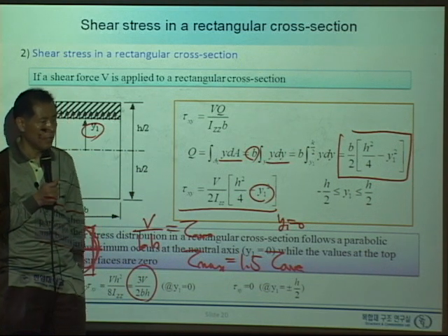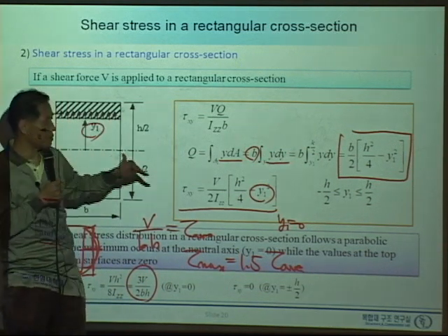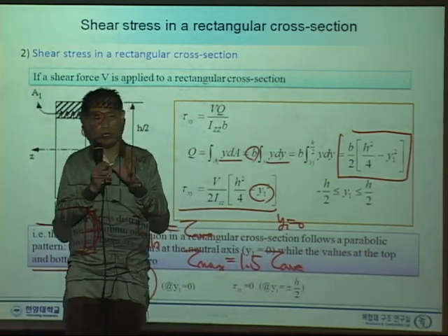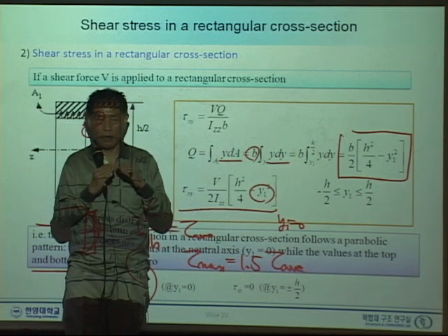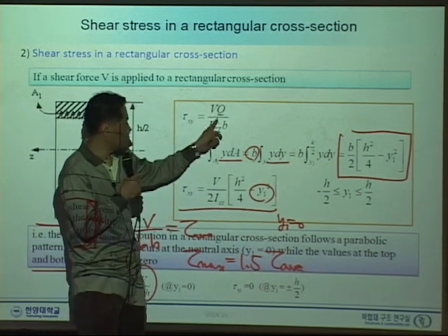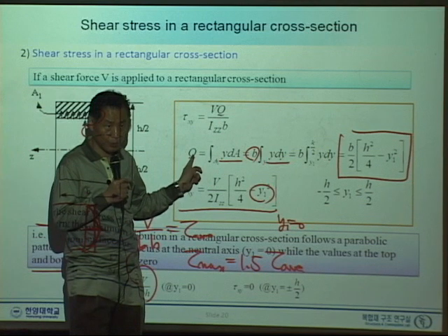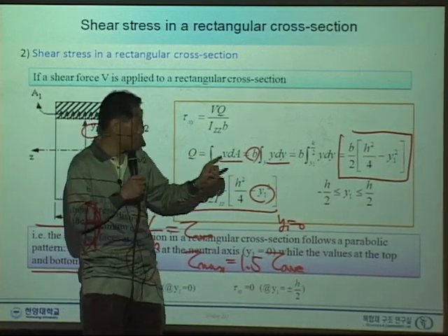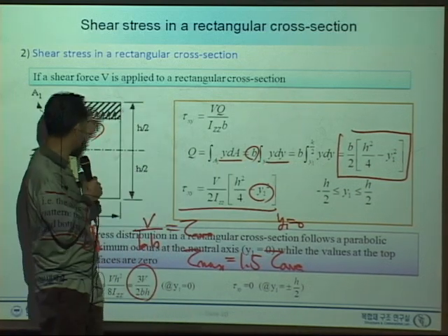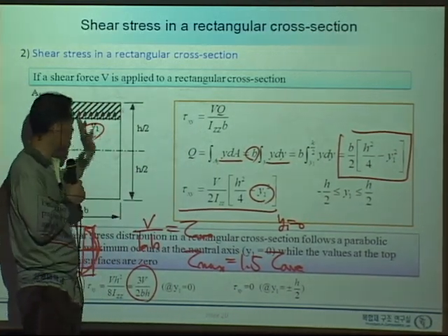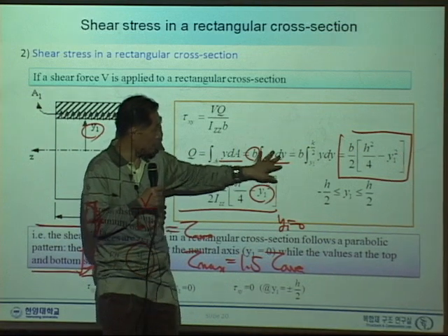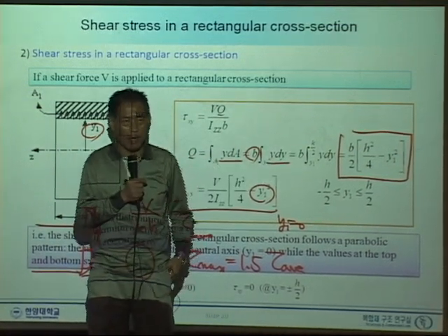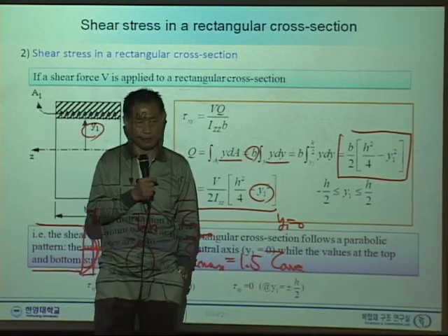Right. Yes. If you consider the same steps, you can simply, whether it is a rectangular, triangle, or any cross section, all you need to do is consider this Q. Calculate this Q and define it as y dA. In this case, it's simply rectangular, but if you have the triangle, you can redefine these integrations, and you will have the maximum at a different location.